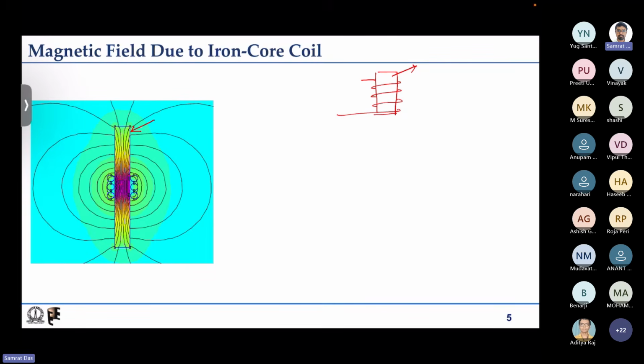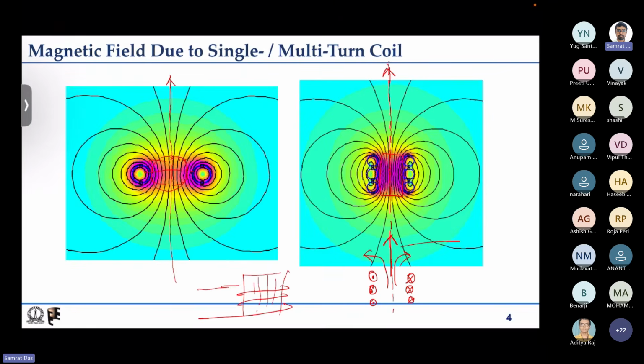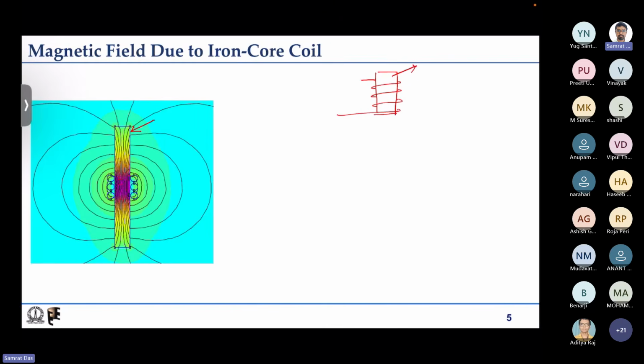If I just quickly go back to the earlier case, you can see electrically speaking it is the same thing, but by putting in the ferromagnetic bar, we are trying to align the flux lines along the ferromagnetic material, because ferromagnetic material provides a highly permeable path, with relative permeability in the few thousands, 10k or even higher.